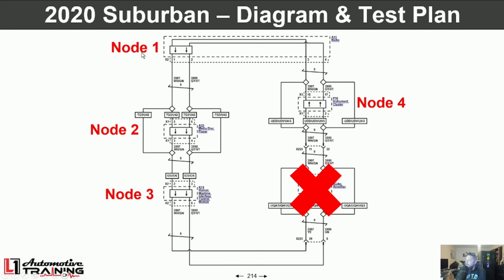You'll also notice the node master indicates the direction of travel. That's how I know that node 2 is media display, not instrument cluster. It is indicated on the modules, the direction of communication flow traffic. You'll see the arrows point down. So it was very important that we get accurate information about this vehicle so we know which direction to test.